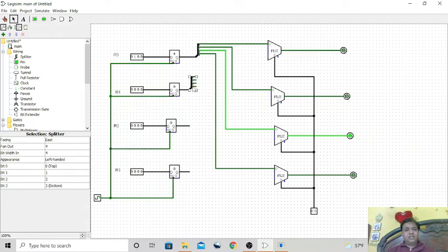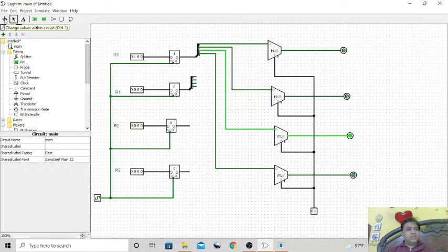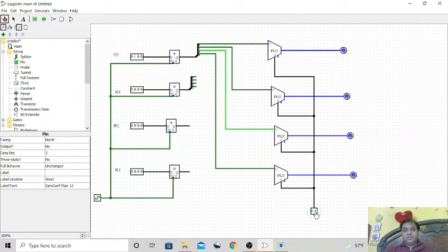That is the R1 register. Now how can the 4 bits be transferred? This register should be selected when the value of the selection keys is 0 1. When it is 0 1, at that moment the first input of this multiplexer will work, the first input of this multiplexer will work, and so on.